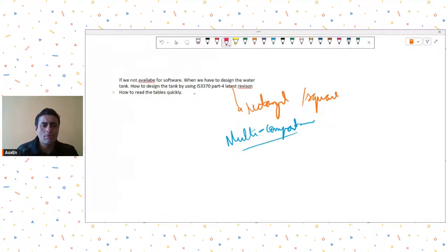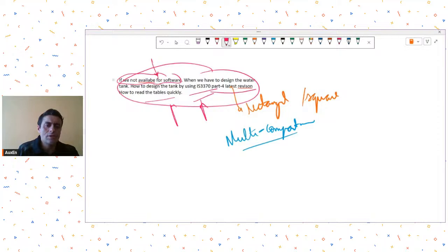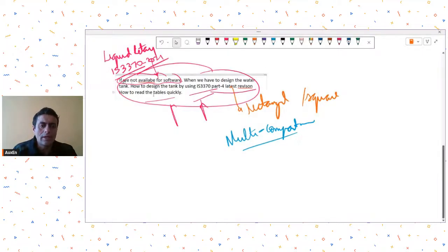So it becomes more and more complicated to use these tables beyond a certain level of complexity in your liquid retaining structure layout. For easy layouts and quick references you can use them, but generally I find that modeling it on ETABS or STAAD is more helpful. We have done an entire course on liquid retaining structures where we have dealt in depth with the design as per the IS 3370 2021 series of codes. So if you have a specific doubt related to tables, please ask.